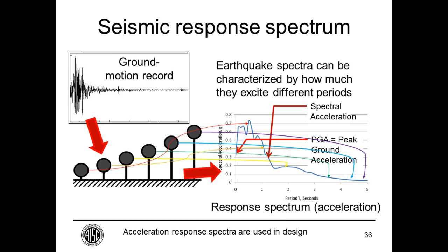That is to say, going out to large inelastic drift and maintaining their integrity. Whereas with low ductility systems, we think if the earthquake force is bumped up by a similar factor, perhaps because they're not well proportioned, it goes from a moderate response immediately to an extreme response as connections fracture and the entire lateral system loses strength.